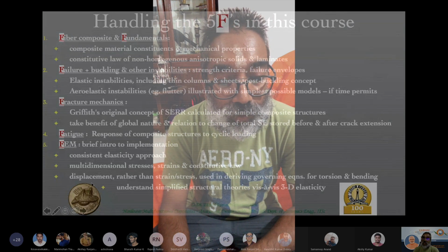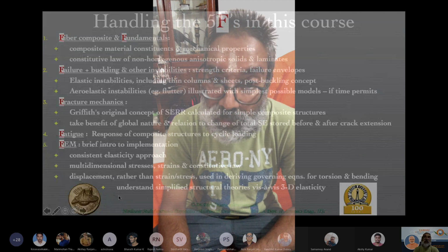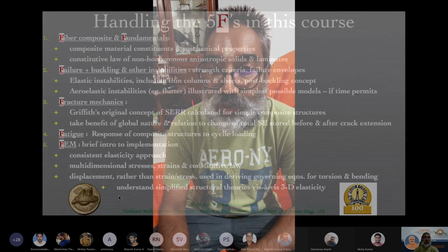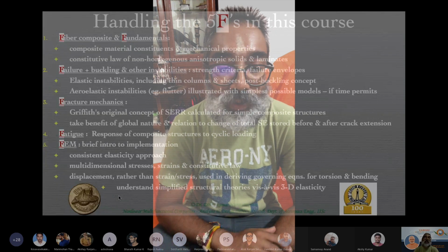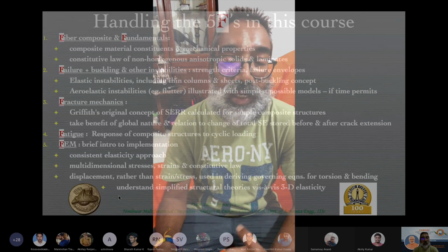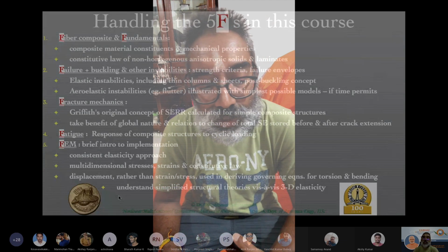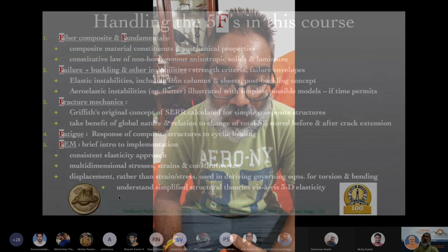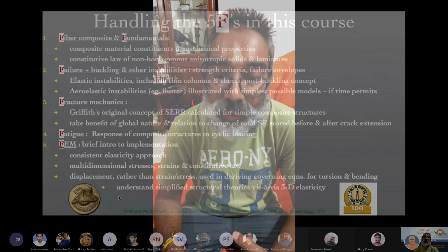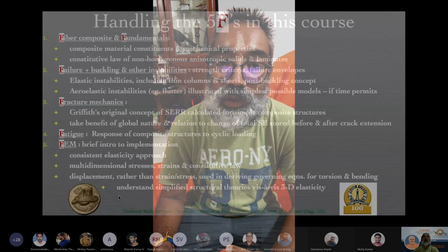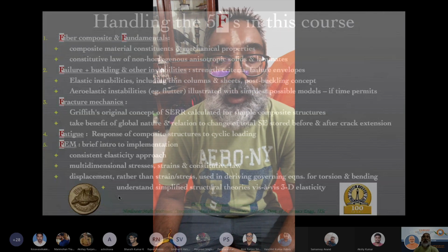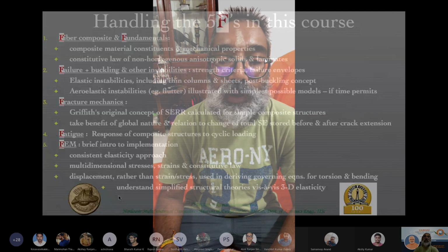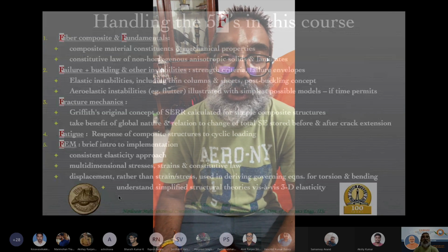Then we will talk about finite elements from a perspective of displacement as a vector, and therefore represented as a column matrix when its numerical values are given. This is again slightly different from some approaches that other people take in terms of a force-based finite element analysis, etc. We will take a displacement-based one, not also a stress and strain kind of an approach, though those would be essential in formulating the energy, strain energy, and therefore coming up with the expression for the strain energy in terms of the strains.